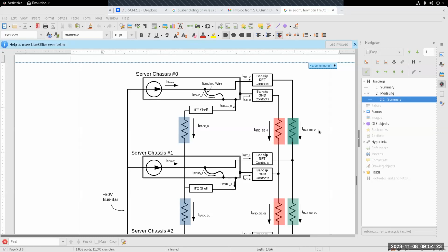Okay. One other point that may help as well, Joseph, to give you some context: I'm aware of the testing that was completed on both of the racks for the OCP base spec, and they went through the standardized ASTM standard of shipping tests, both impacts and shock and vibration testing. And we didn't see any failures related to what you mentioned that you've experienced in the past. We didn't see any failures either. It wasn't until the equipment had been installed for 6 months that we started having servers dropping out, because the bus bar corroded to the point, due to fretting corrosion, where we weren't getting good power anymore.